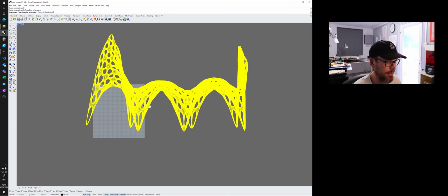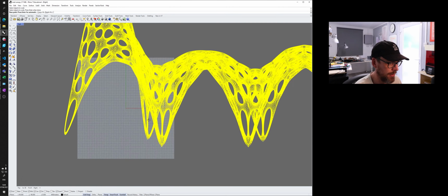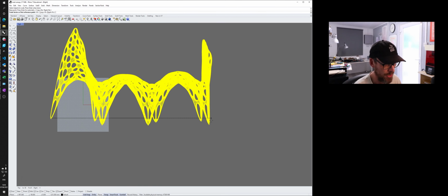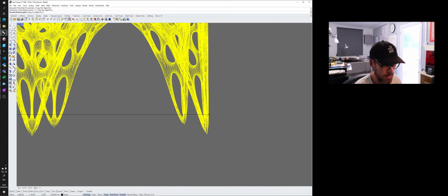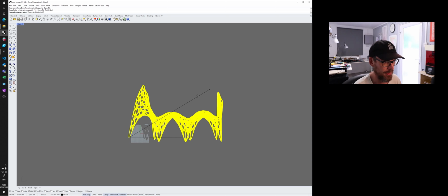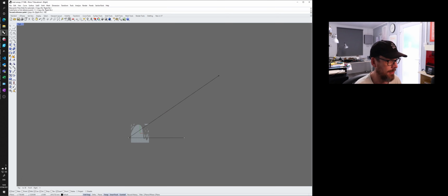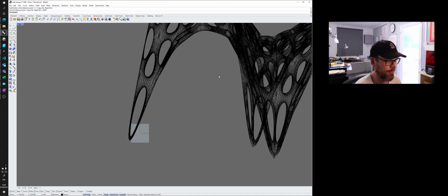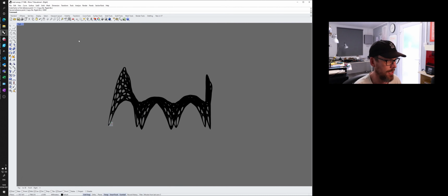I'm going to use the right view in this case, and I want to make sure I choose over here. So about there, this looks reasonable to me, and I'm going to go all the way over to the right hand side. Let's go to there. I'm going to hold shift to make it constrain, click, and now I can type 10,000, so 10 meters.